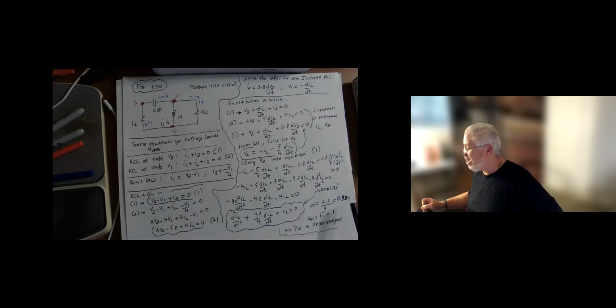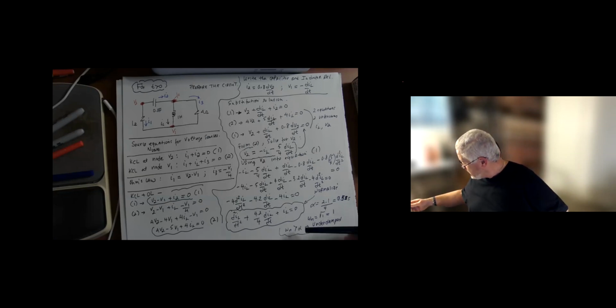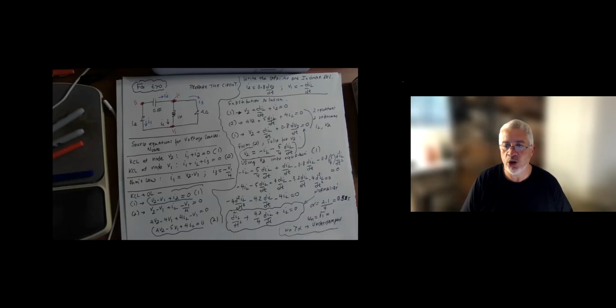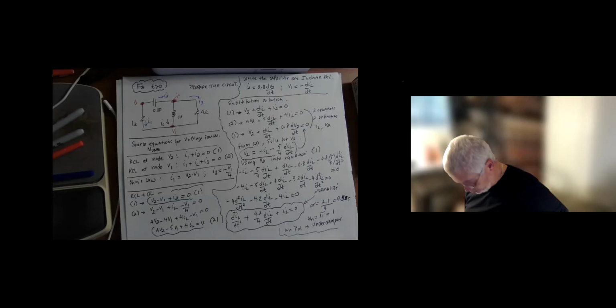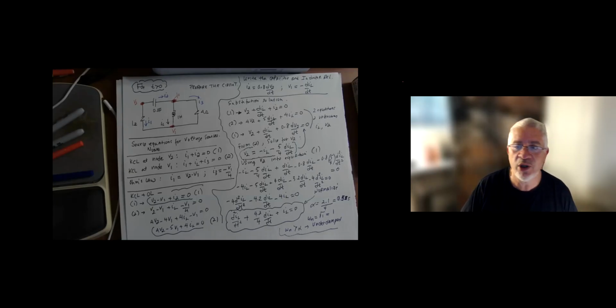So that's 0.525, and then omega n is the square root of 1, which is 1. And then we've identified that obviously omega n is larger than alpha, so this is an underdamped example. So I'm basically going to now show you how to solve for the solution for an underdamped example here. Let me go quickly to the PowerPoint slide to show you what I'm talking about.